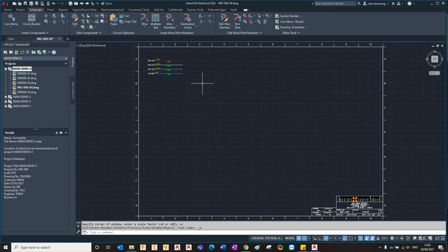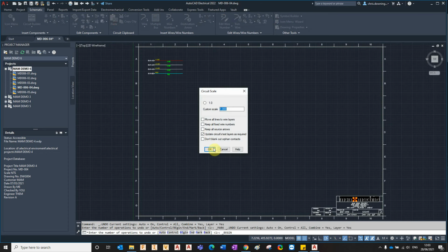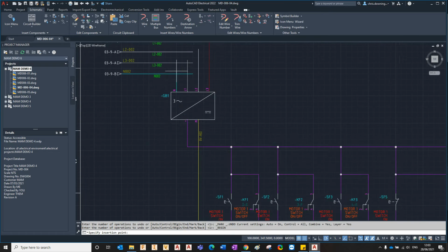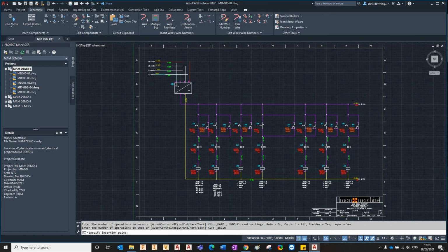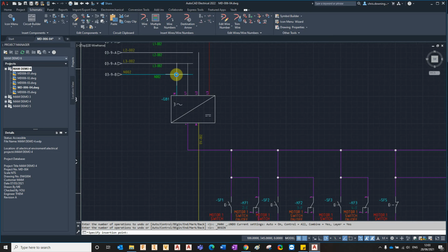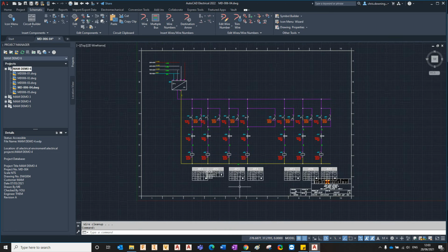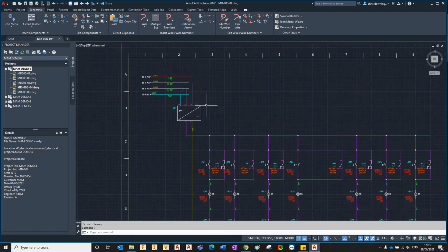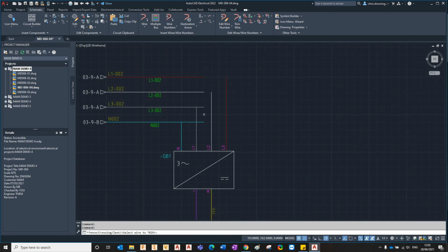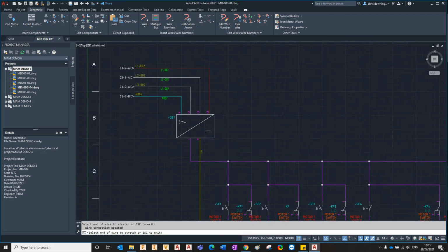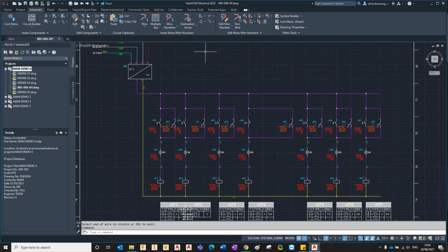Don't need to save it. And then use the paste to paste that new circuit, or the circuit, onto this page, like so. It goes through then updating all the numbers and the cross references where required. Okay, and then I can trim these wires as well, or extend them. In this case I need to extend a couple, like so, nice and easy. to make modifications like that.